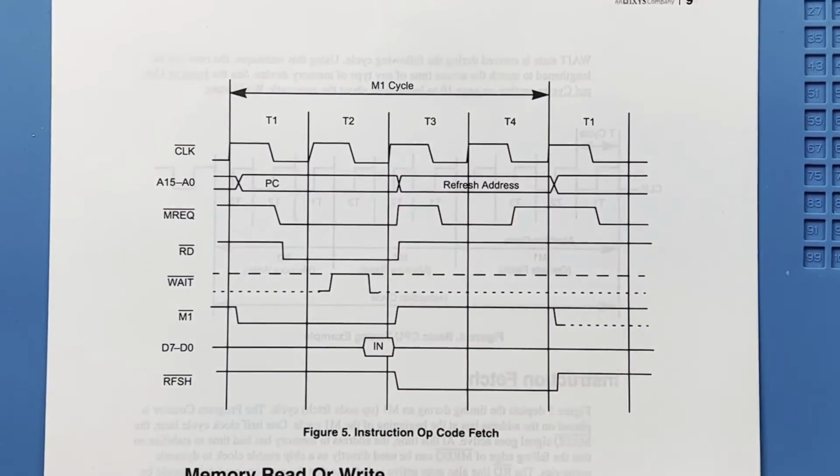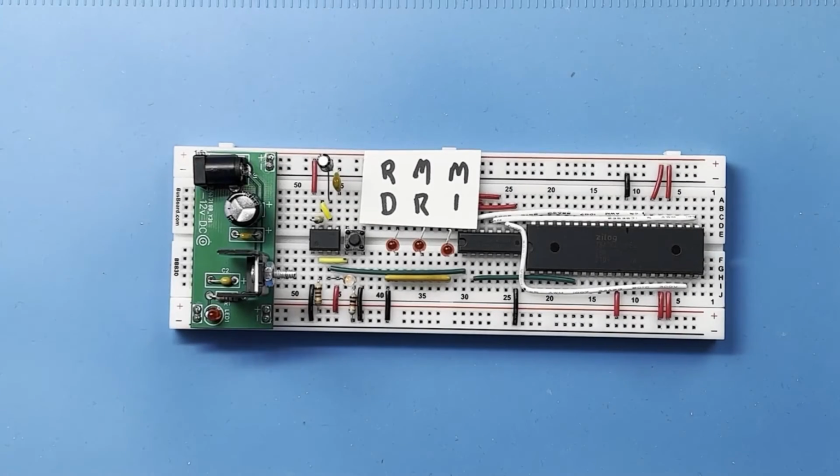But this time the program counter contains a 1. This will effectively give us a 64K binary counter on the address bus. So we should be able to tie data low, hook up LEDs to the address bus, and see it counting in binary. So let's do that.